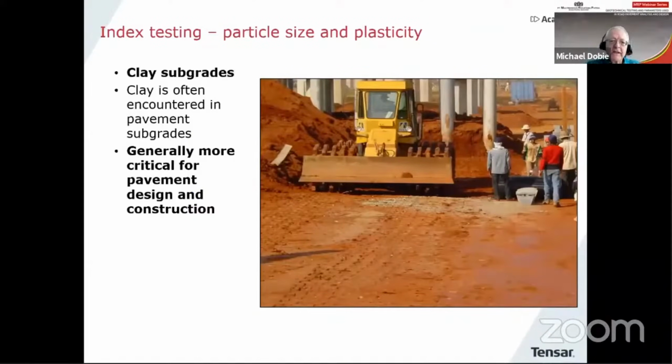Let's talk a little bit about clay. Now, clay subgrades, really, that's the main topic today. If you have nice granular subgrades to build pavements on, you're not going to have much of a problem and your pavements will be quite thin. But the bigger issues come with clay subgrades. And so they are generally more critical in pavement design and construction. So we will concentrate on them today.